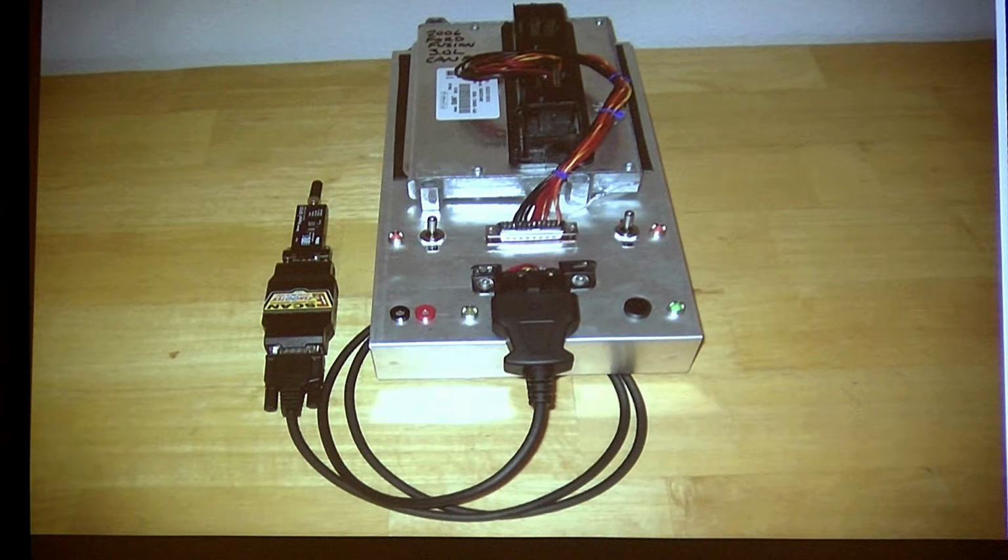You always got to factor in that if one of your 5-volt references is pulled to ground, you could pull the 5 volts down in the micro. If you remember back in the late 90s, early 2000s, you would pull down your 5-volt ref from a cam or a crank and you couldn't talk to the car. Be really careful with that on newer cars.